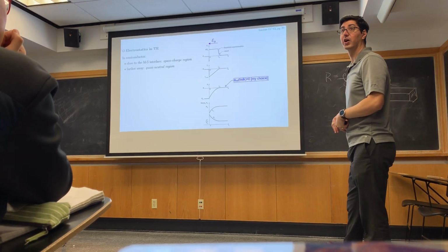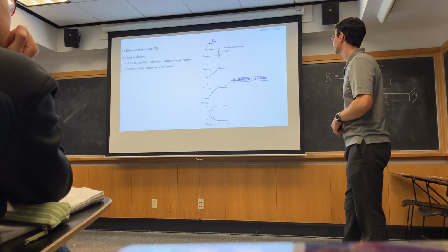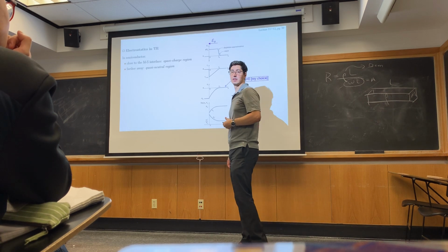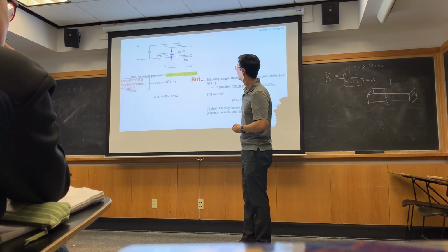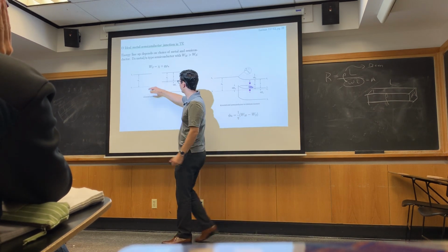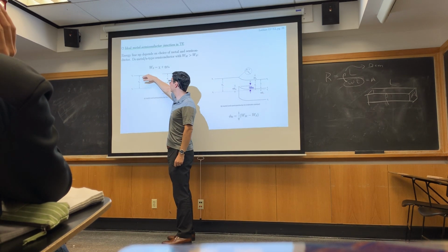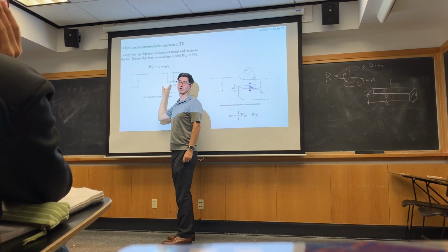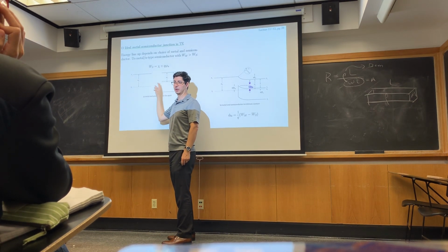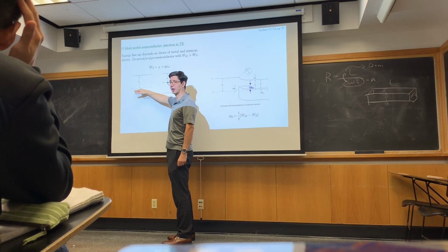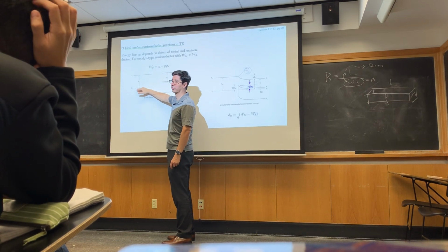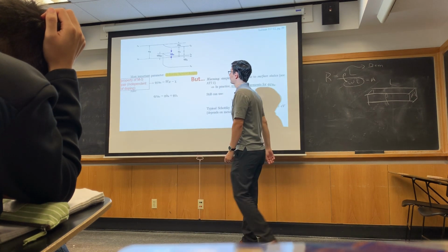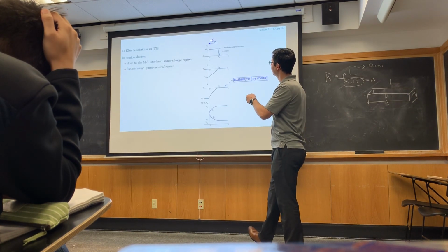Now that was all talk. Now let's get into the mechanics of it. Okay? Electrostatics and thermal equilibrium. We're assuming that the metal could be anywhere, right? If the Fermi level of the metal was up here, electrons are going to transfer into the semiconductor. That's not going to create an electron barrier. But we're going to assume that the metal is down here with the Fermi level below that of my n-type semiconductor. That's going to deplete my semiconductor.